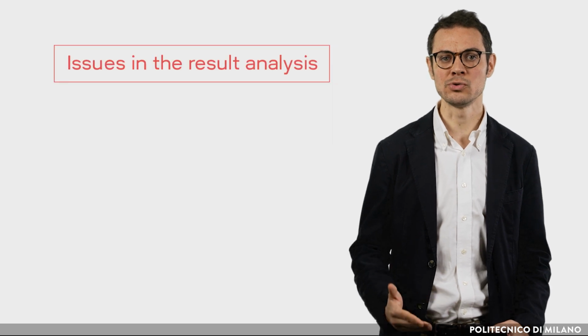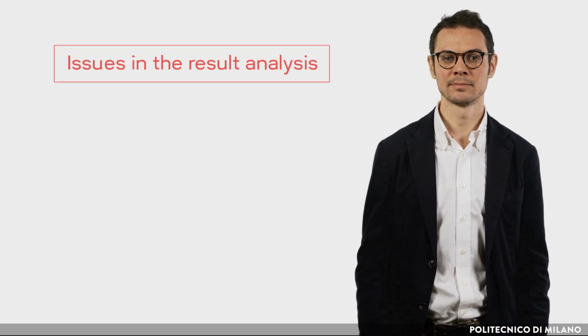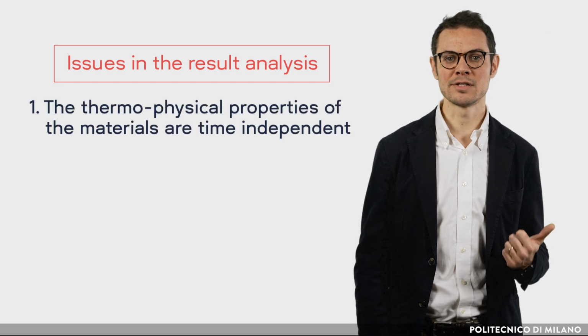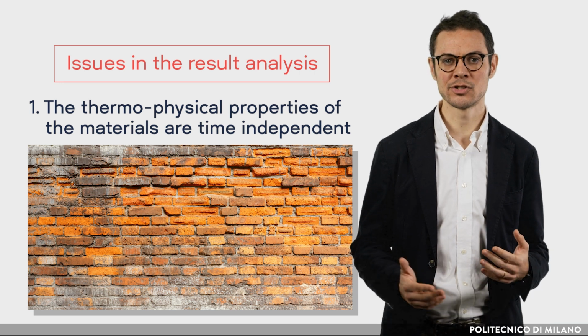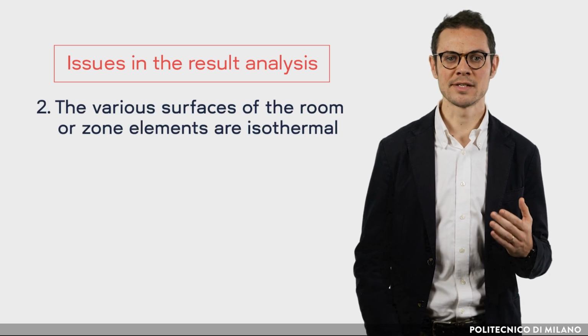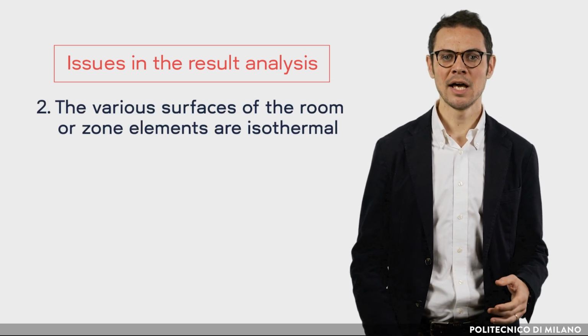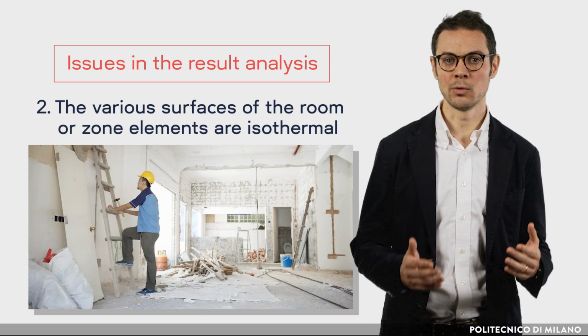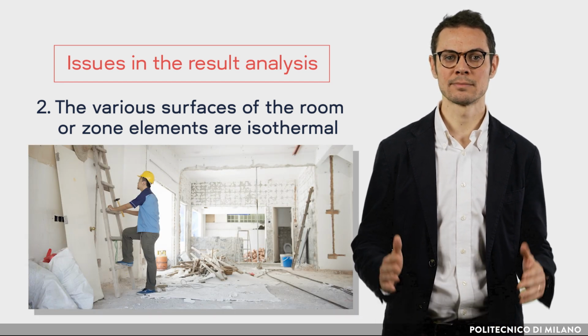Finally, since some errors can also be made due to the numerical model that may not adequately capture certain physical phenomena, the energy expert should consider also the following issues in the results analysis. First, the thermophysical properties of the materials are time independent, so phenomena like degradation along the time are not considered. Second, the various surfaces of the room or zone elements are isothermal, so the walls are considered homogeneous.